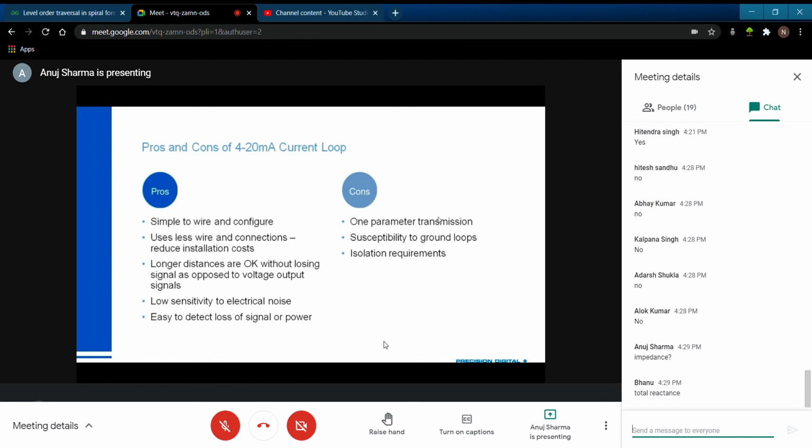As you get more and more complicated with the information you're trying to acquire, it might be time to start looking at other things, such as HART, which is a serial protocol that runs on top of a 4 to 20 signal, or Modbus, which I mentioned earlier. Things start to get complicated, and all of a sudden you're finding yourself managing a large number of loops. In those circumstances, there may be better alternatives.